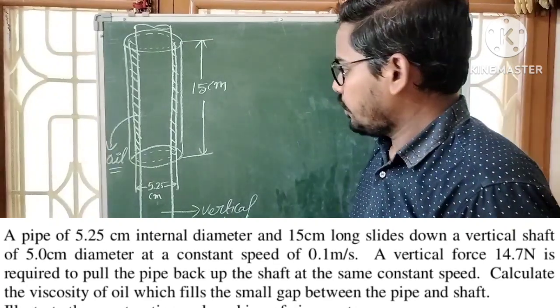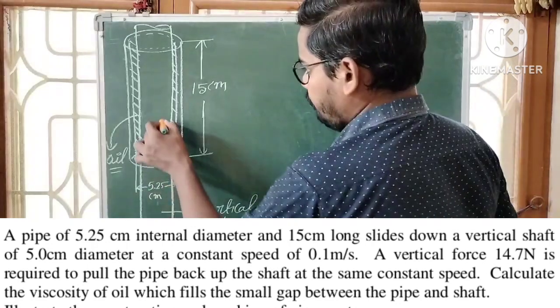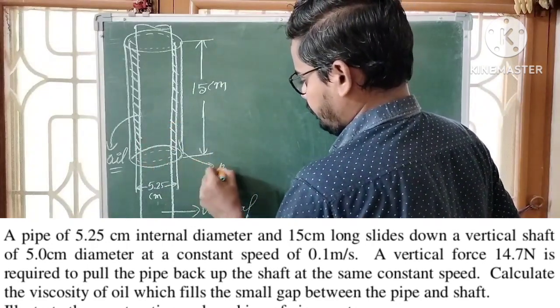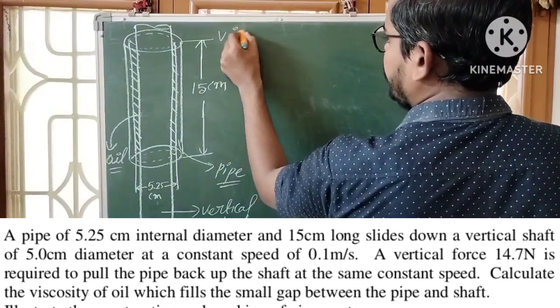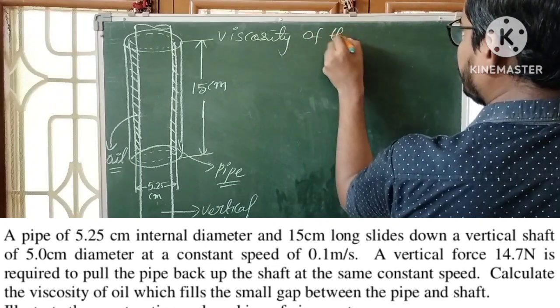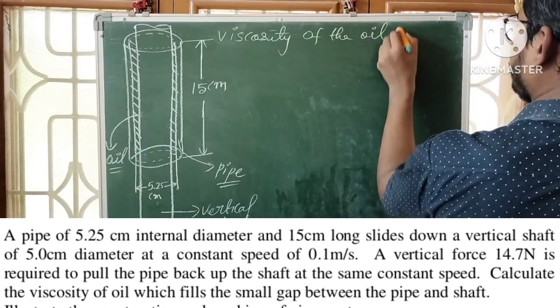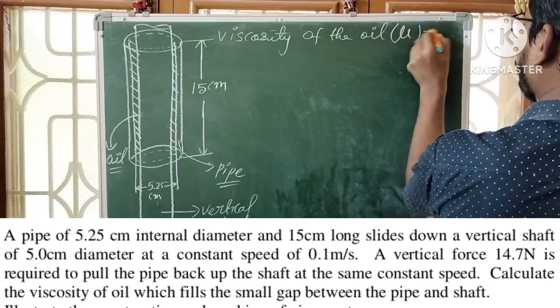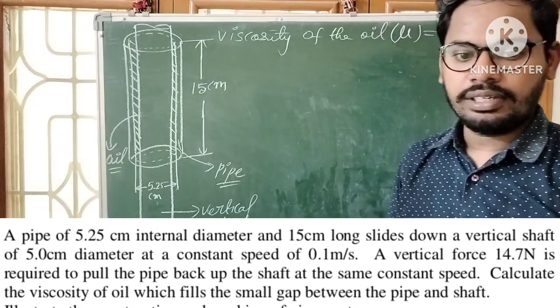So, small gap filled with oil, and this is the pipe. So at last we have to find viscosity of oil. In this problem we have to find viscosity of the oil, denoted by mu. Here mu means viscosity of the oil in Pascal seconds or Newton second per meter square.